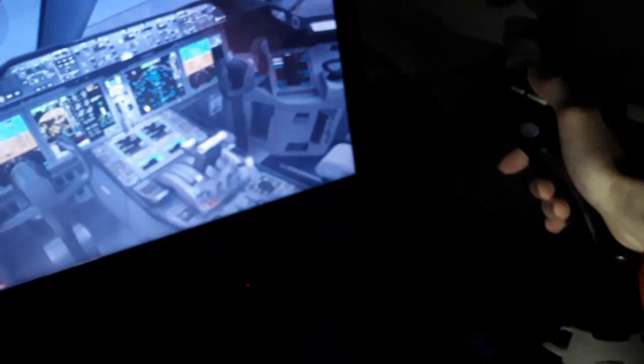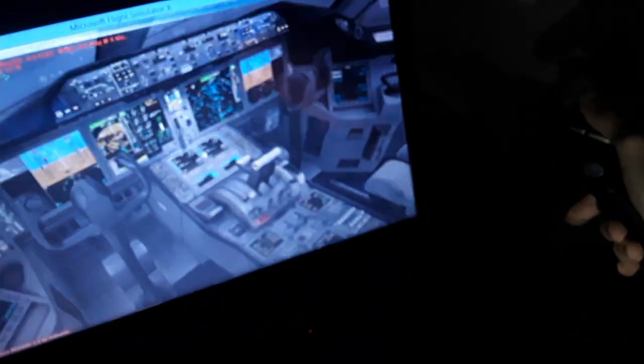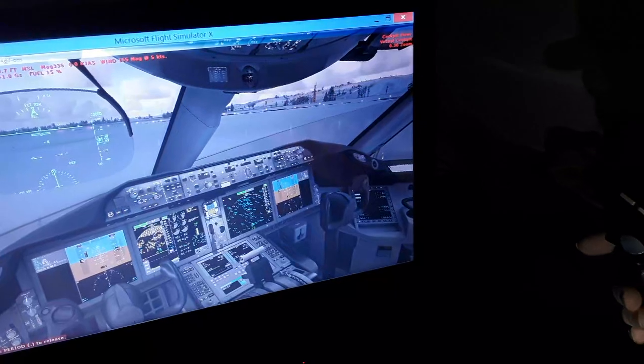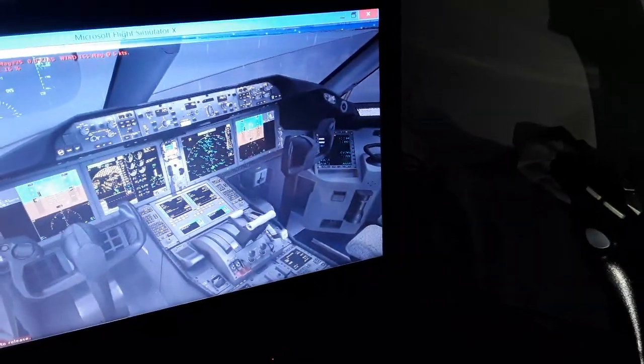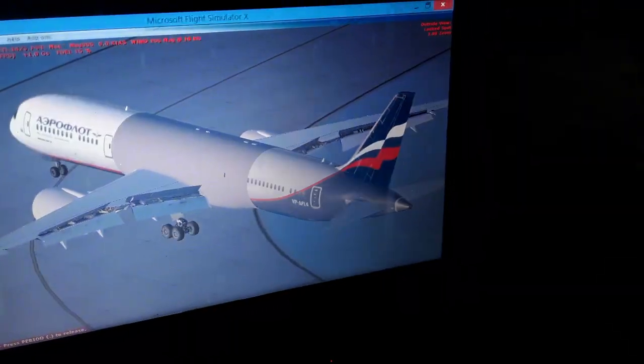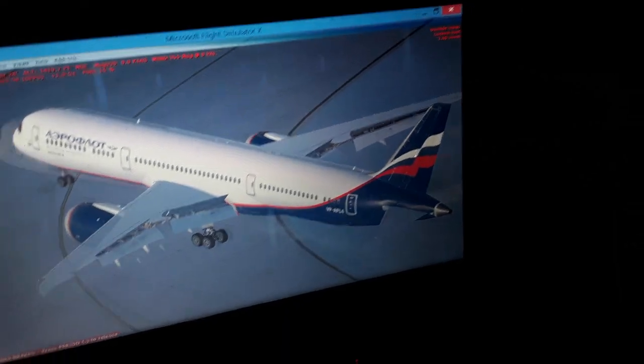So we apply thrust. We're gonna use the side stick in the Airbus side stick down, push forward, and also in the Boeing the yoke push forward to decrease the angle of attack, and advance the thrust levers forward like takeoff setting, full thrust setting, until we increase the airspeed. So we need to balance in the air we reach the stall speed.